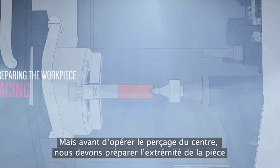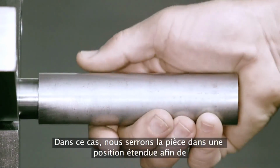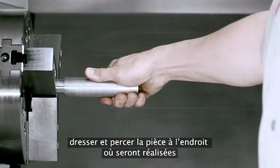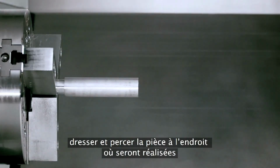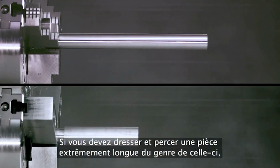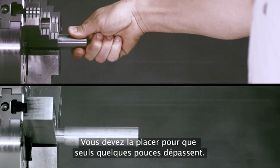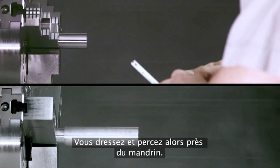But before center drilling, we need to prepare the end of the workpiece by facing it off. In this case, we grip the part in an extended position in order to face and center drill the part in the same place where the turning operations will occur. If you're concerned about facing and drilling an extremely long part like this, you should choke up so only a few inches are hanging out, and face and drill close to the chuck.